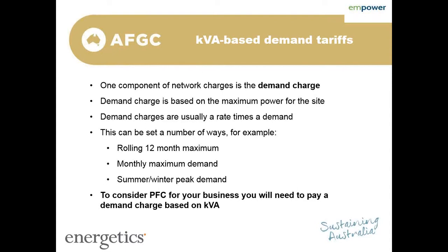So the take home from all this, to know whether power factor correction is suitable for your business, is that you need to have an unbundled tariff, so you need to be able to see your demand charge there, and it needs to be based on the kVA rather than kilowatts. Some sites might just charge your demand on your active power, so it doesn't really matter what the power factor on your site is.